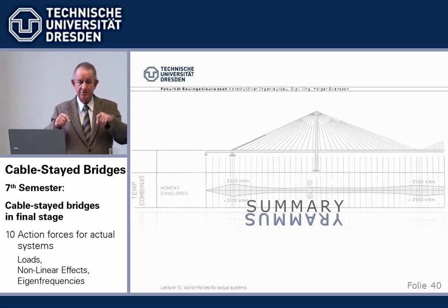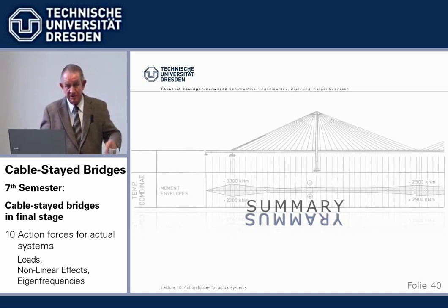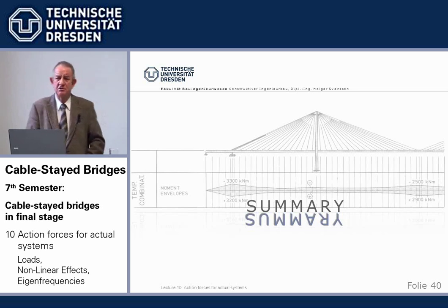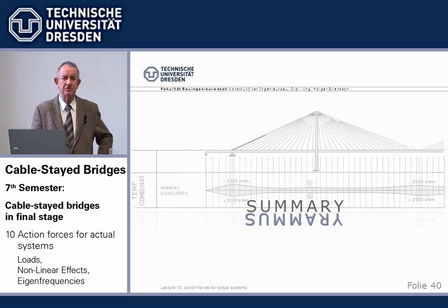And then you tell the computer, give me a set of cable forces, give me a set of cable shortenings, which in effect, if added to the dead load on the elastic system, give me this run of moments on the rigid supports. The computer gives that to you, and you can come there by iteration and all sorts of things. But I expect you to understand that.